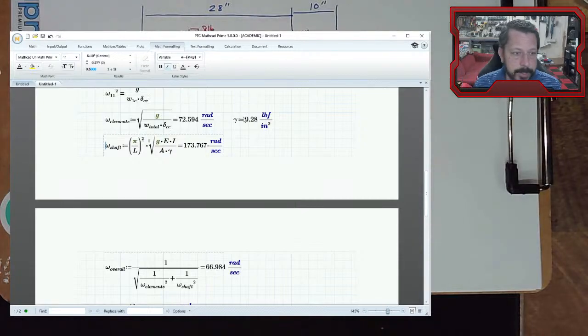So this is equation 722 in your book that calculates the critical speed of just a shaft. Now it is a solid shaft with no changes in geometry, so no steps or anything. That's a limitation of the way we're doing this, is that the shaft is solid. Pretty much if the shaft is stepped in a way that you think that's going to matter, then you're going to have to do a numerical solution on this to integrate across the whole thing.